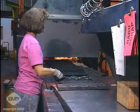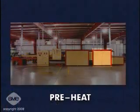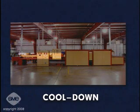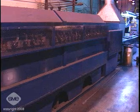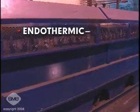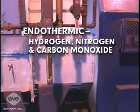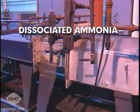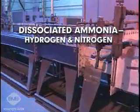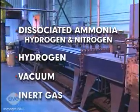After pressing, parts are transferred to the sintering furnace. Sintering furnaces include preheat, high heat sintering, and cool-down zones, each having a controlled atmosphere. Depending on the base metal of the part, the atmosphere of the sintering furnace may be endothermic, which is composed mainly of hydrogen, nitrogen, and carbon monoxide. Exothermic, which is composed mainly of nitrogen. Dissociated ammonia, which is hydrogen and nitrogen. Or entirely hydrogen, vacuum, or inert gas.